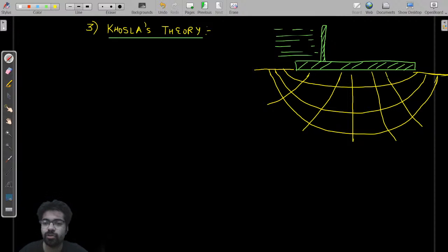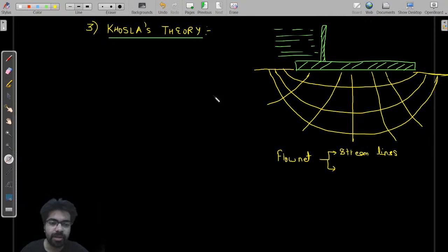So you all know this is your flow net. This entire thing is your flow net. And in flow net, two types of lines are there. You all know. One is your streamlines, my dear friend. One is a streamline between which actual water flows. Okay, between these streamlines, this is your first streamline, second one, third line. Obviously, water will flow in between this line, like this, from one point to another. It will not creep along the length of the floor. He has told that water will flow according to Darcy law. It will follow the concept of flow net. Okay, in a homogeneous soil, you all know.